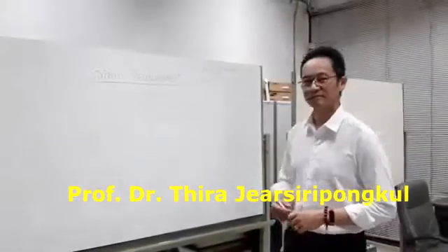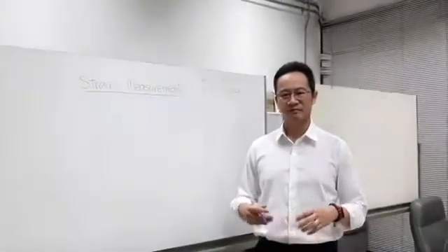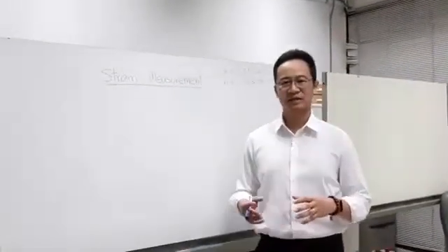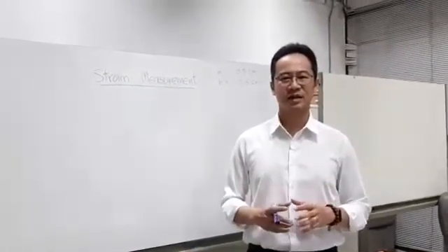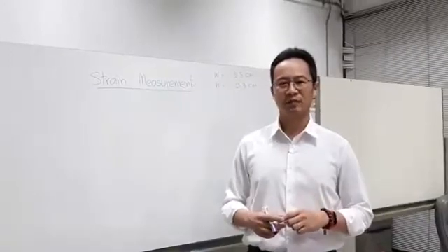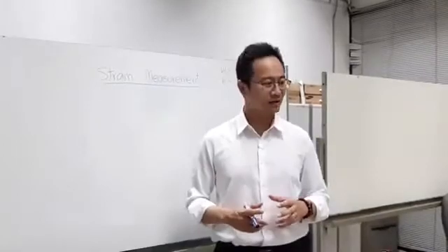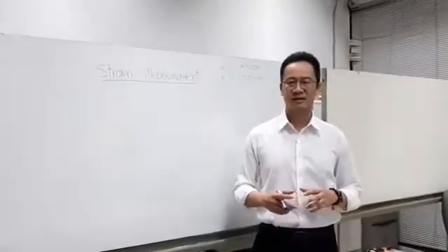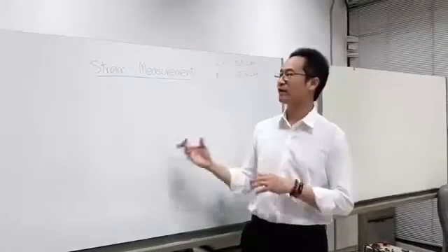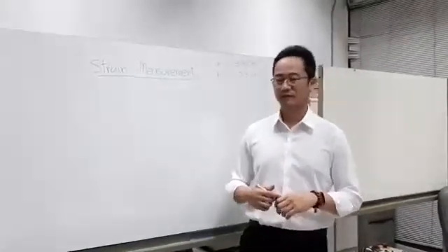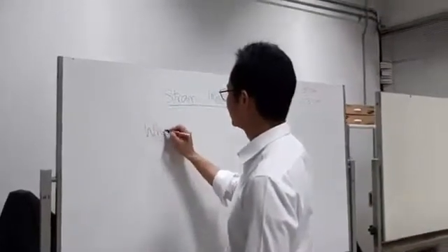Hi students, the laboratory today will be a strain measurement. Firstly, I'm going to show you the introduction of the theory that concerns the laboratory. There are two parts. The first part is the electronics, with the circuit you need to use for the measurements. And the second part is the mechanical problem, and how we find the strain for the measurement. So the first theory we call the Wheatstone bridge.